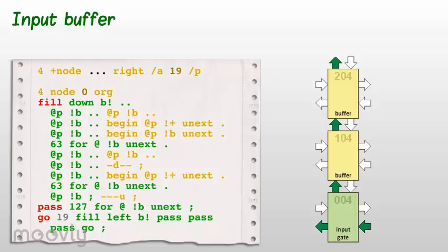Now we can have a look at what word fill does when executed. First, fetch_p store_b ... is sent to node 104, which effectively converts this node into a wire node ready to pass one word where its register B is pointing. This is to the node 204.